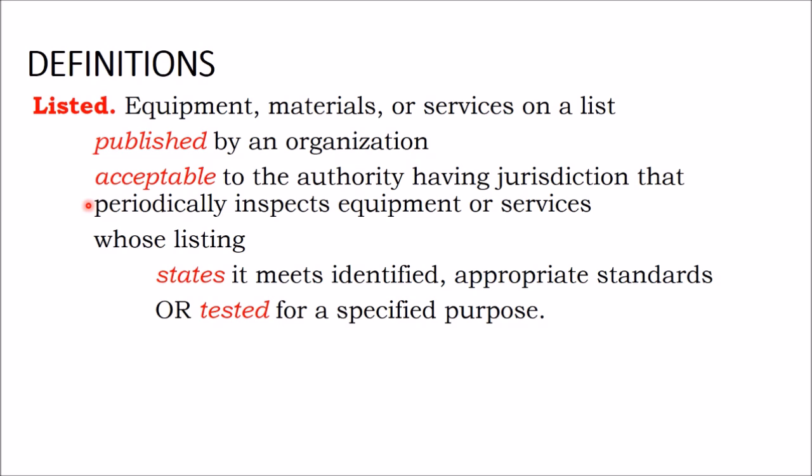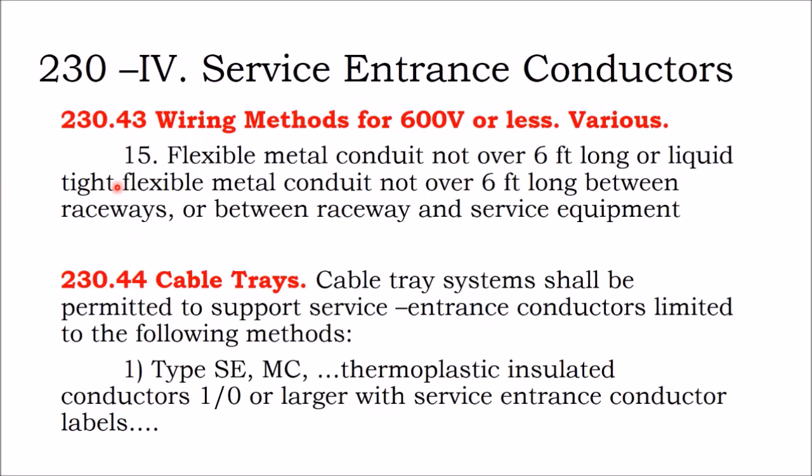And so you might find the greatest splice kit in the world that's made for underground cabling, and you want to go use it up on the rooftop for your solar array. If it's not listed for use on a roof for solar electric wiring, you may fail your inspection. They have to be listed, and not just listed, but listed for purpose.